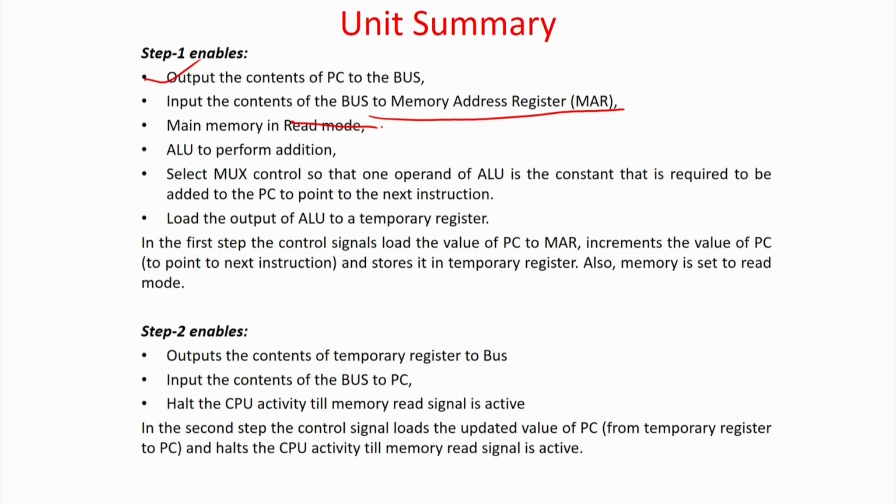Based on the contents of the program counter, you will load the instruction, because the memory address register tells where the instruction is to be obtained from, and it will be loaded into the memory buffer register, or the memory data register.